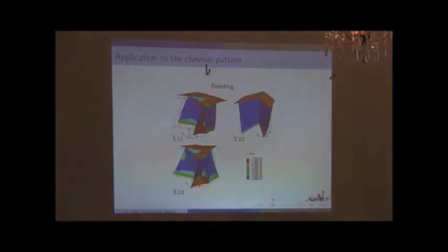What you see is the numerical confirmation of what I just said: when you bend the RVE, the skins are mostly put into traction and compression, and the core is not actually loaded. And this is von Mises, von Mises in the sense of Abaqus, which is a bit weird, but anyway.